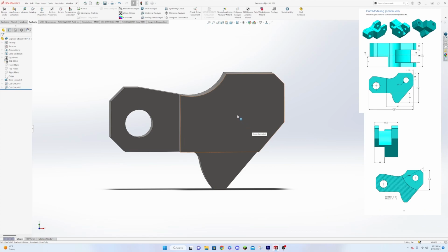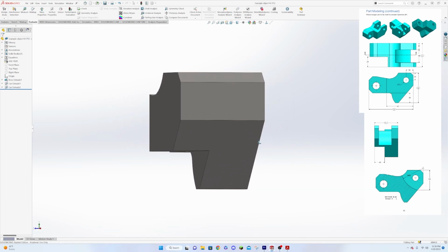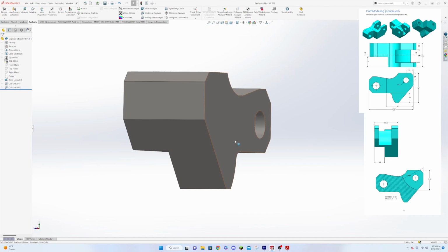And so what we'll want to do is, you can see on here that this is getting referenced to the back side of that object, and it's going to be 12 in from the back side of that object. Once again we could do the math and figure out where that plane is going to be in reference to the front plane, but it's easier if we reference it to this back side here. So we'll come over here and click on this backside, and we will